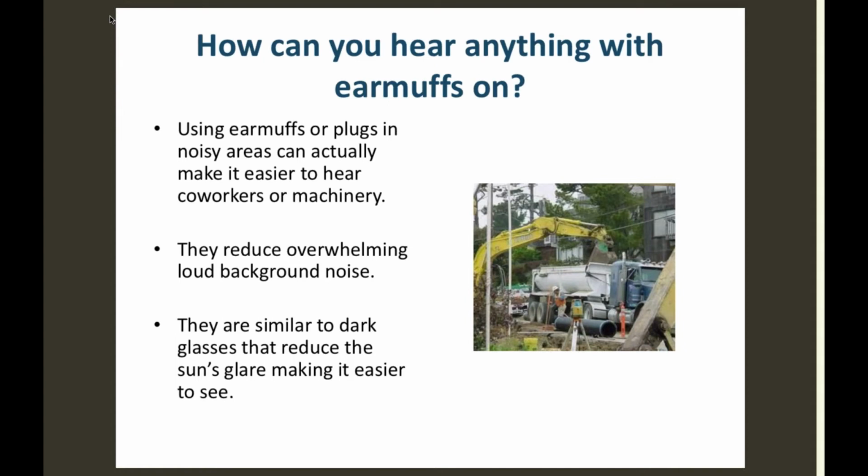But on an airplane with that constant buzz of the engine, it almost completely erases it, right? So they're designed for environments where we're in a car or something like that, a moving vehicle. They really seem to work pretty well. But in other environments, they don't seem to work that well. And you saw that graph that showed that those earmuffs at low frequencies don't really attenuate much, but at higher frequencies, they attenuate quite a bit.